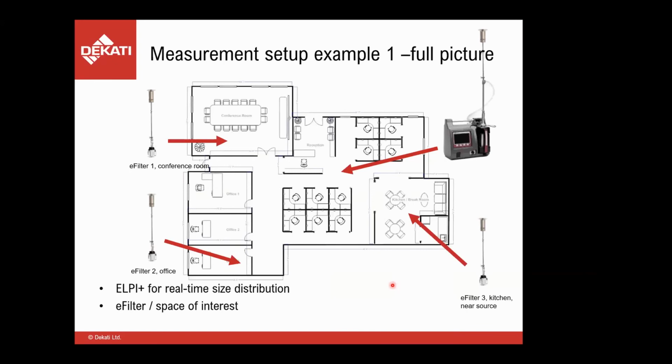A very comprehensive measurement would be to do a center point measurement of size distribution and concentration of the aerosols, and then do, in this case, reference measurements at different specific places with E-filters that might be the most interesting sources or expected sources to be measured.